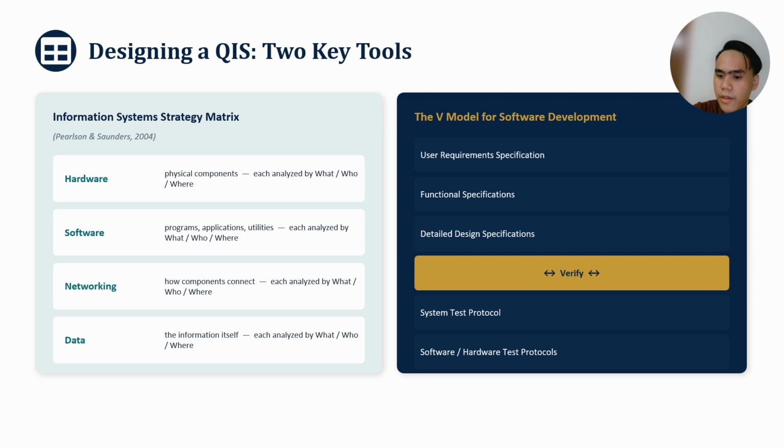So one very practical warning from the chapter is that tasks that seem trivial, like naming conventions for sensors and PLCs, can have a huge downstream impact. So imagine building a downstream report for a packaging area with hundreds of PLCs and thousands of sensors. A good naming convention lets you capture a whole group of related variables in a single database query using a wildcard. Without one, the user is stuck specifying every single sensor individually. So the same care applies to test protocols themselves.